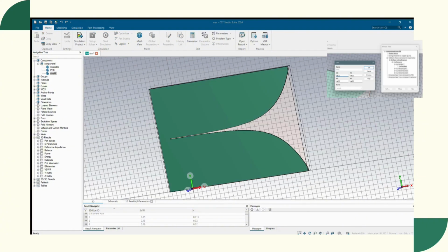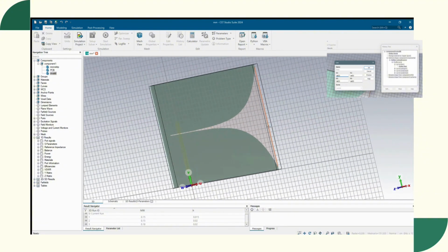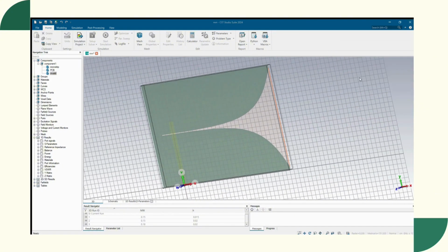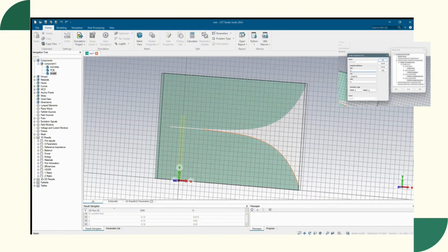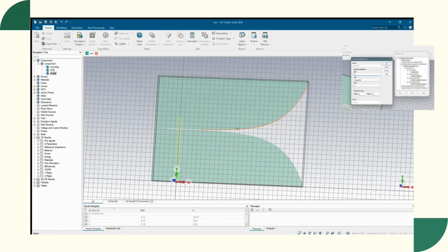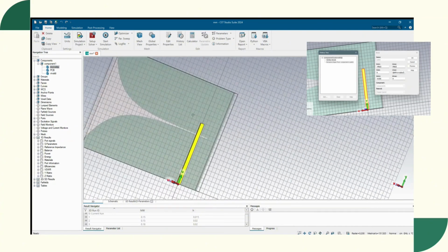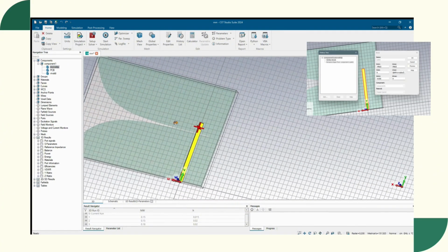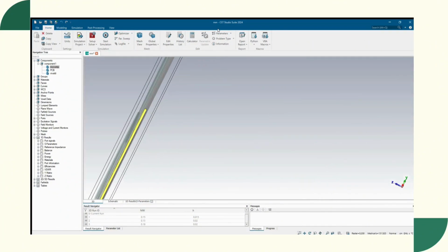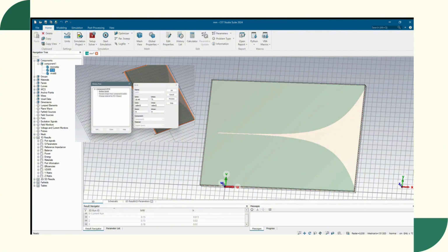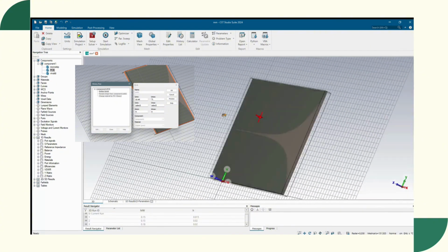And then how I make this kind of shape, this curve: first I make the front line at the front of the antenna. I name it line 1, and then the gap between the two curves I name the polygon, which is the center with the microstrip feed line. Lastly I name the analytical curve, which is the bottom of the curve, and analytical 2 is the top of the curve at the top of the antenna. Then I design the microstrip feed line, where the height and the thickness of the microstrip feed line are also crucial for this design. And then I use the PCB board using material of FR4.